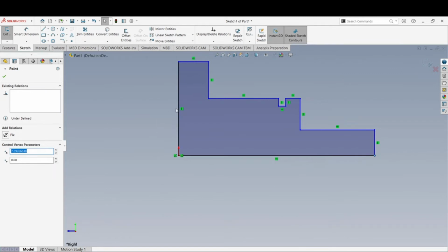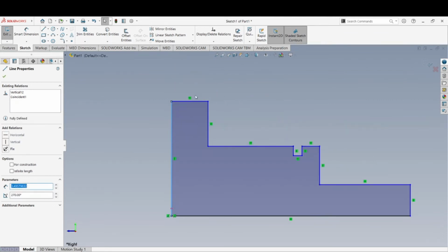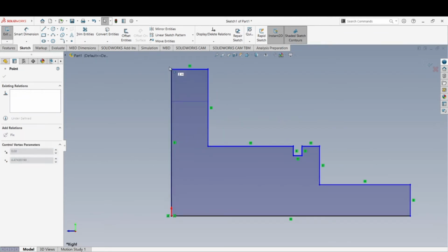And exactly the same thing with this line. It is locked into the center point down here, coincidental to the center point of SolidWorks, and it has a green vertical constraint, or relation. With that, this line cannot go left or right. I can't drag it left or right, but I can take the endpoint and go up and down with it on that same line.